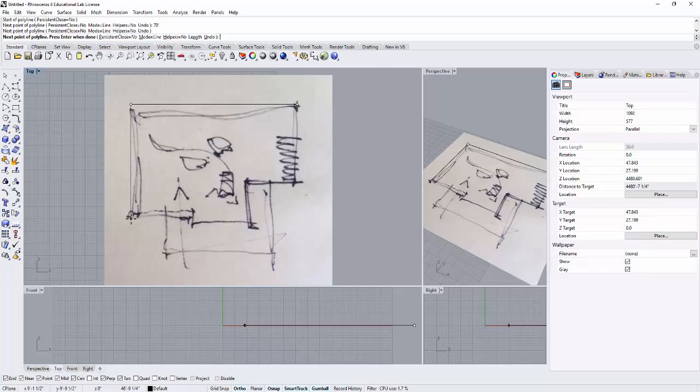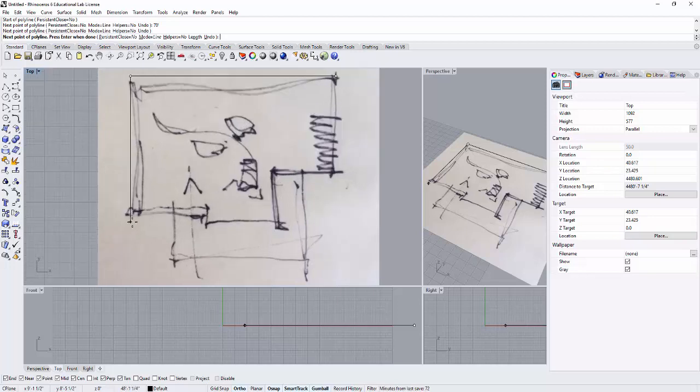And then I'm going to come back this direction. My napkin sketch here was not precise at all. So what I'm doing is I'm looking down right here at my actual dimensions. I'm going to lock in some dimensions that I know are close. I'm reading this as moving in the Y direction, 45 feet, roughly. So I'm going to go ahead and type that in and accept that as an exact dimension.